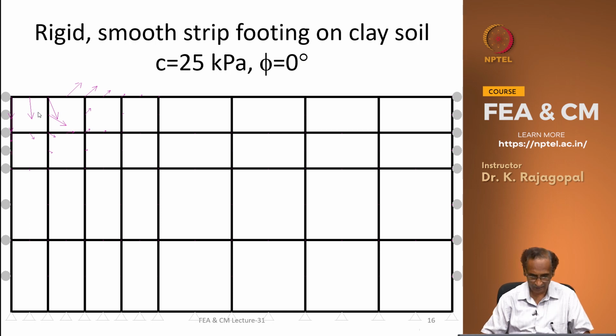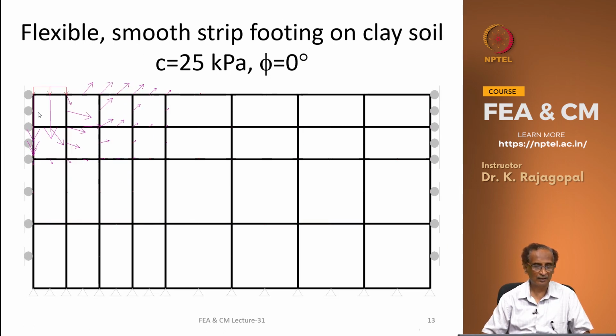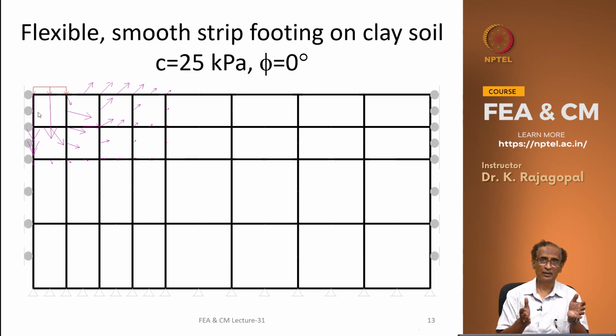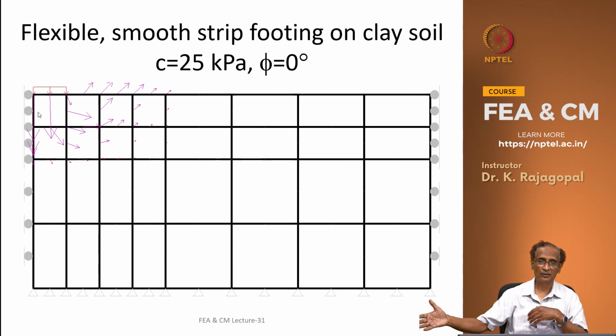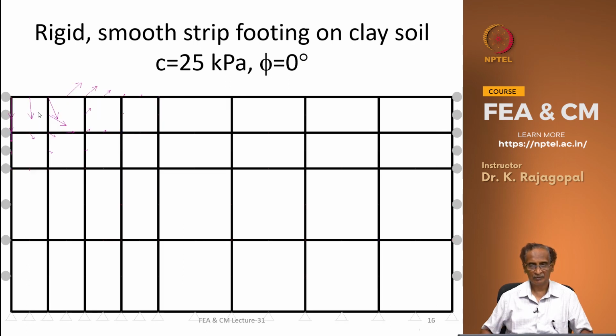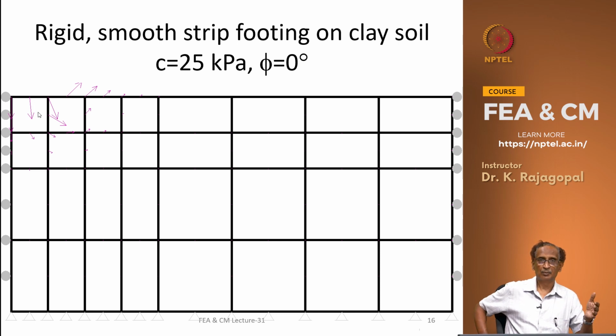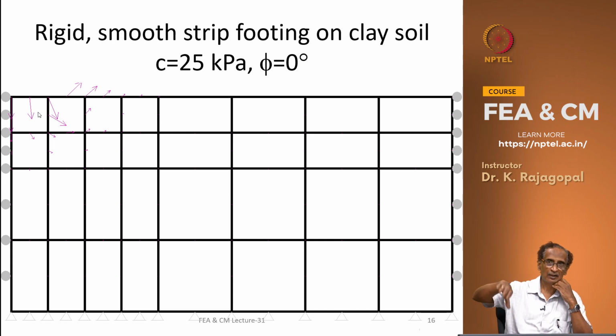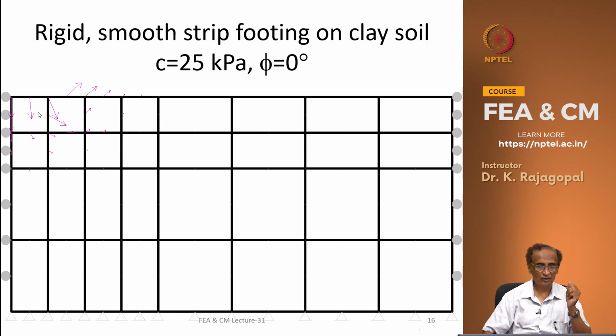So, you see the effect of load control analysis. With load control, once you apply the pressure on the surface, it has to naturally spread to a longer depth and width, because the pressure has to disperse. Whereas with the displacements, we represent a better distribution, because if the soil elements around the footing fail, then you get a localized slip surface. That is what we see here.